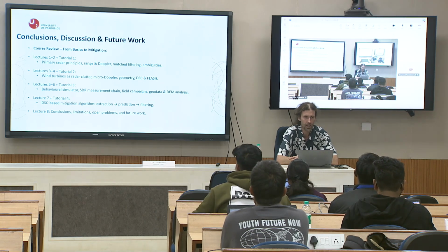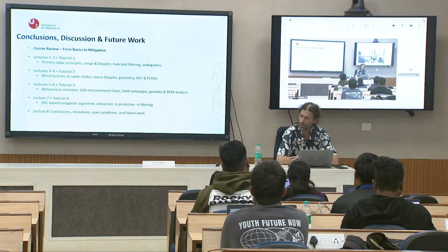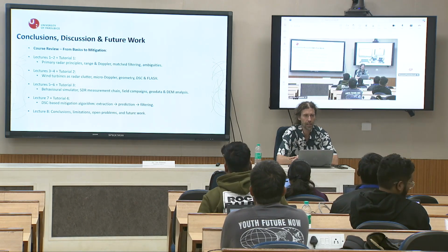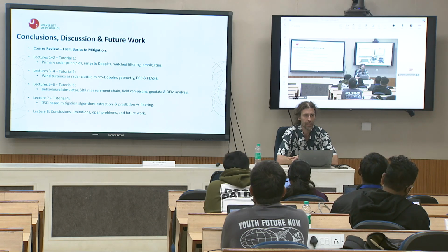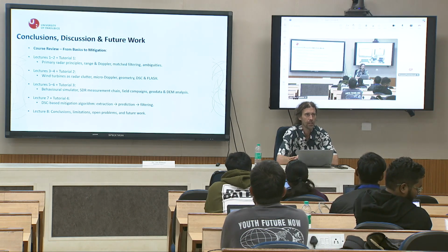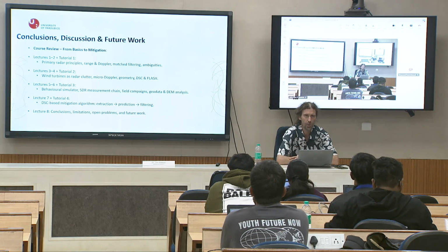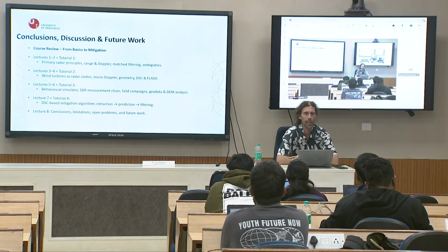Then I want to highlight how important before any measurement is analysis, like geo-analysis through map, through digital elevation model, and through line of sight. You can't use just only a 2D map, but always check real terrain.